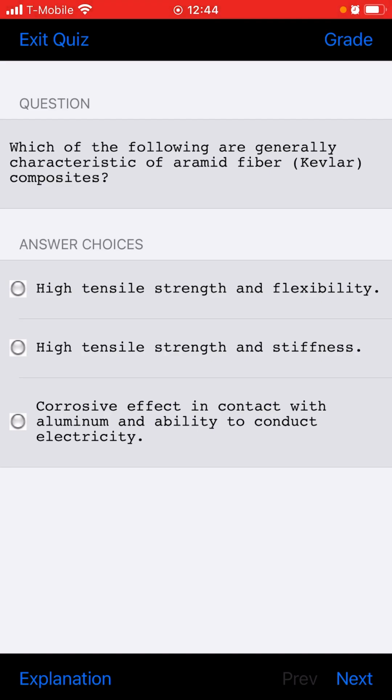Let's read this. Hole filling fasteners such as conventional rivets should not be used in composite structure because of the possibility of causing delamination. When the conventional rivet is driven, its shank expands to completely fill the hole. The force applied by the expanded shank will cause the material to delaminate around the edges of the hole.